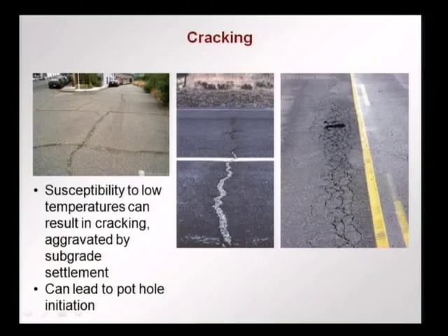You have a lot of cracks that develop along the length of the pavement, and when these cracks join, a pothole develops. A piece of the asphalt concrete comes off due to traffic movement and a pothole starts, and this develops further and further as the aggregates and the binder come off and water is driven into the asphalt concrete by traffic and rains.